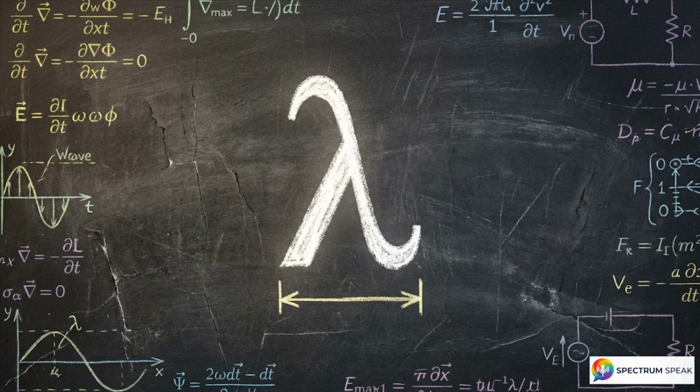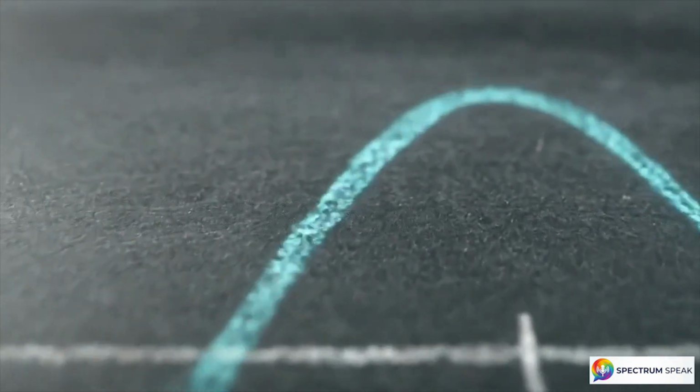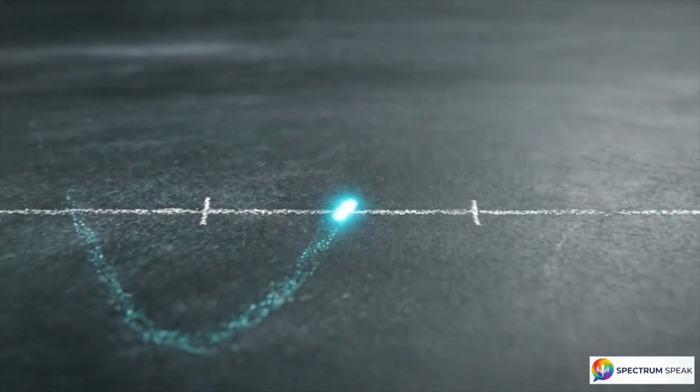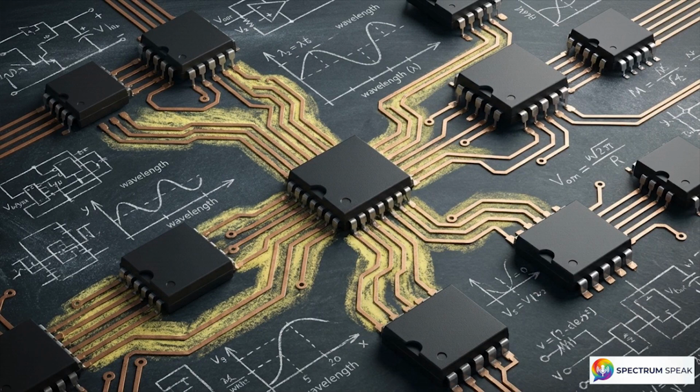To quantify this phase shift, we use wavelength, denoted by the Greek letter lambda. Wavelength is the exact physical distance a single-frequency electromagnetic wave must travel to change phase by 360 degrees. This diagram shows wave propagation over distance c. The full cycle defines 1 lambda. Its length is governed by a simple equation. Wavelength equals velocity divided by frequency. As frequency escalates into the gigahertz range, the distance required for a phase shift shrinks drastically. Calculating this exact wavelength is the mandatory first step before analyzing any printed circuit board layout.